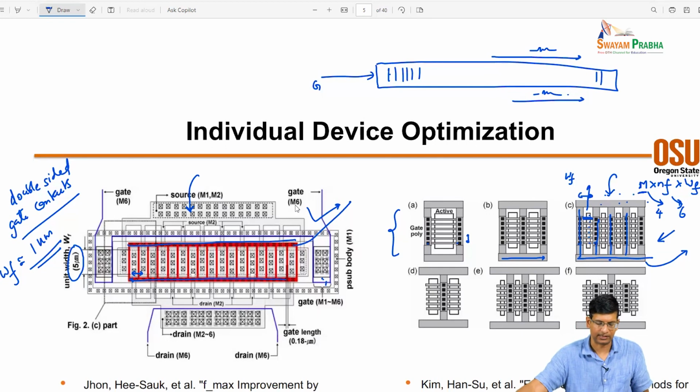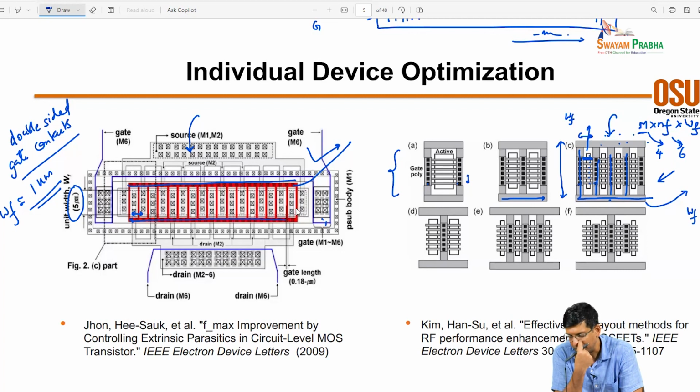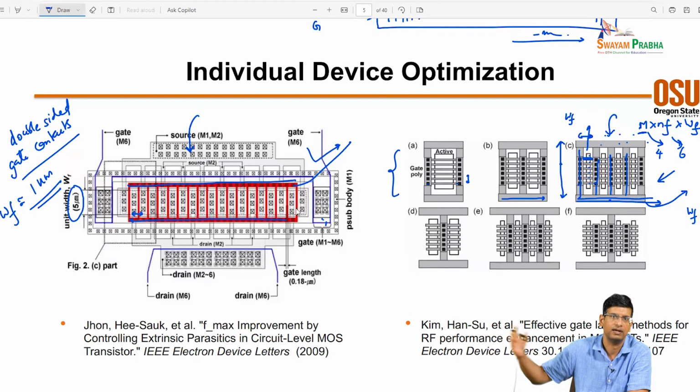It's a good question. I'd say it's frequency dependent, but the width per finger is usually somewhere in the 1 micron to 2 micron range depending upon frequency. And then on this side you can typically live with a 10 to 20 micron device size with an RC extraction. So if your device is more than 1 micron times however many fingers can fit inside 10 microns, then you start going along this dimension and start building an array.